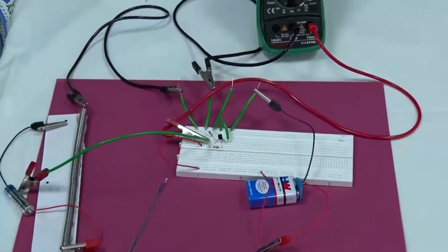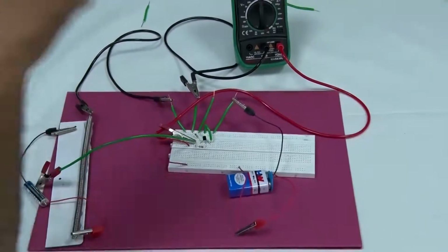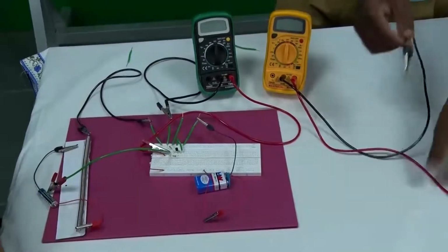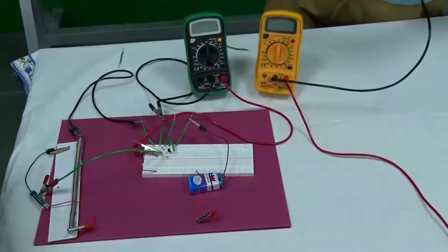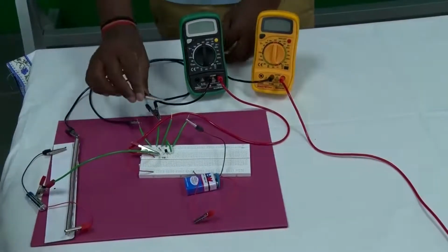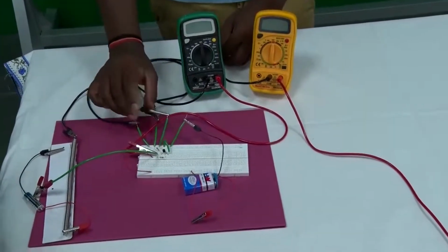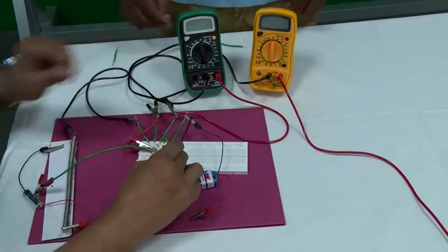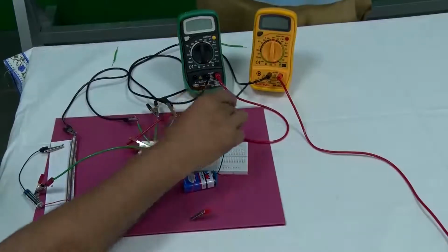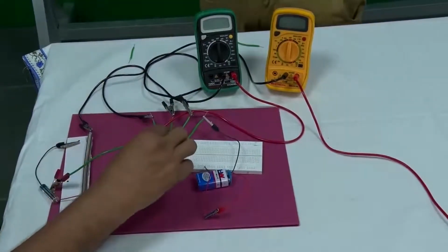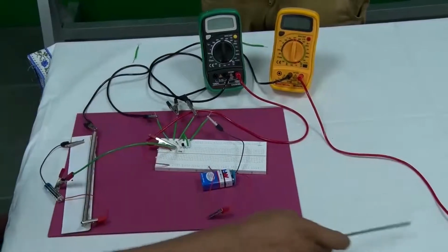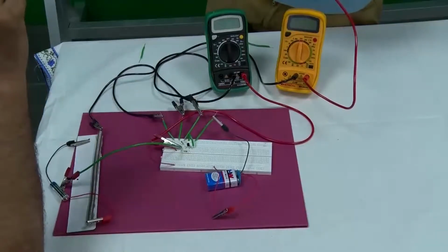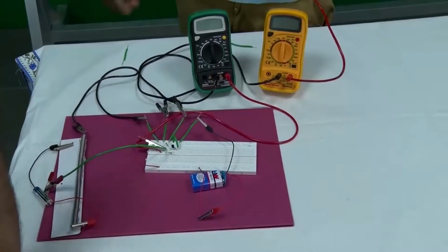Then the output side. In the output side, once again the black terminal should be grounded, 0 potential. So, see how the circuit is implemented nicely. This is also at the same potential. All those negative terminals, all those black leads, they are joined together. And the positive red terminal should be measuring VO, the collector. So, it has to be directly connected to the collector.